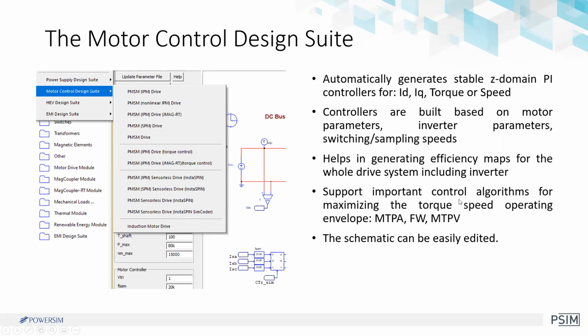And then the control algorithm working there, not only the outer and inner loop I talked about. Actually, the reference currents we are generating, ID and IQ, are optimized ID and IQ based on your speed, wherever your speed is. So if your speed is less than base speed, we'll be doing optimization based on maximum torque per amp, MTPA. Field weakening after base speed: we have some back EMF, and we will be doing field weakening to weaken the stator flux by making ID more negative. It's a very fundamental part of FOC, field oriented control.